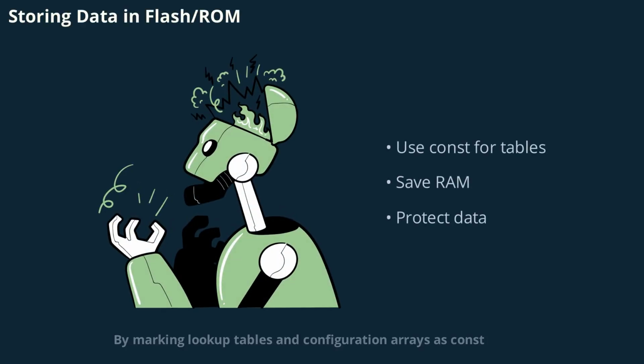By marking lookup tables and configuration arrays as const, you ensure they are stored in flash or ROM instead of RAM. This not only saves valuable RAM but also protects your data from accidental modification. It's a best practice that every embedded engineer should adopt.